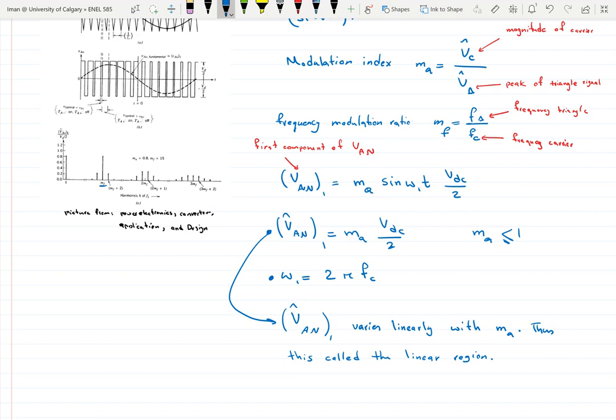So remember, because this is the harmonic side, it would be MF multiplied by FC, which would be FS. So this is really FS, and then this is 2FS, and its sidebands plus 1, plus 2. This is how the harmonics basically show themselves.